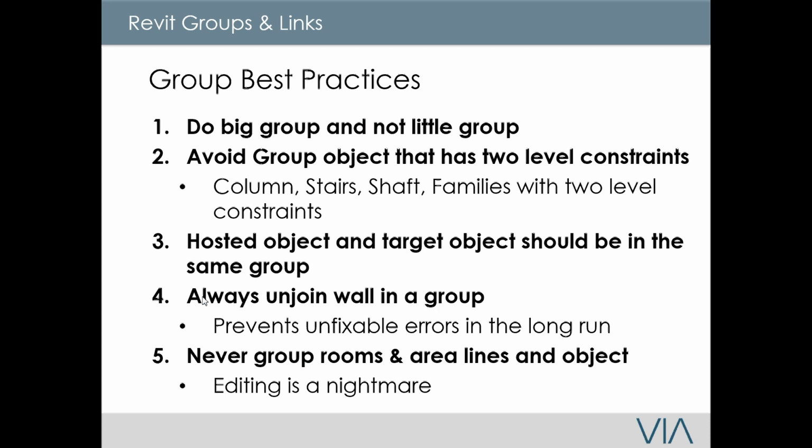Never group rooms in area boundaries, because editing is very, very bad. I'm going to demonstrate later on why it is bad. The problem with the room is that it's very flaky. It tends to want to stick to a level. So if you do have a level offset, there's a chance that the object will disappear from your group.